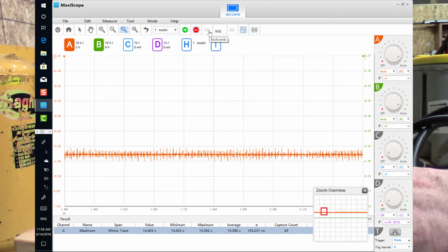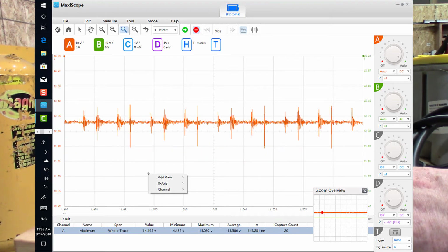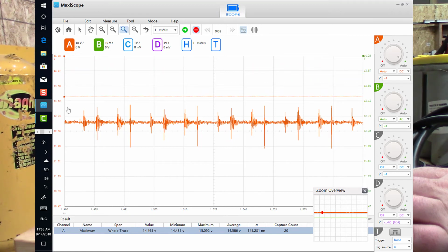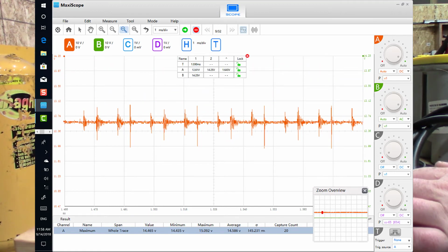So in this scenario, I cannot control how much amperage I'm putting on this load. So right now, my battery loader goes to 135 amps instantly. But what I want to show you is this. Look at the voltage that was maintained by this supply. We maintained 12.61 volts. So we're still over that 12.5 volt minimum, with 135 amps of load on it.